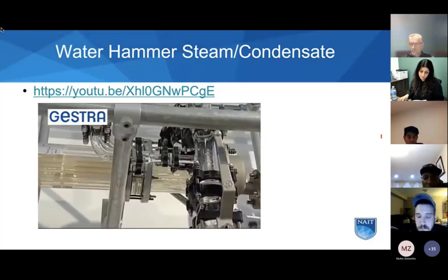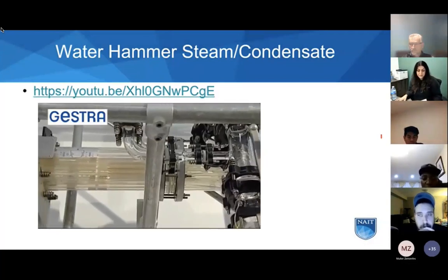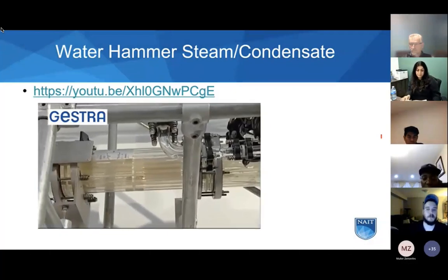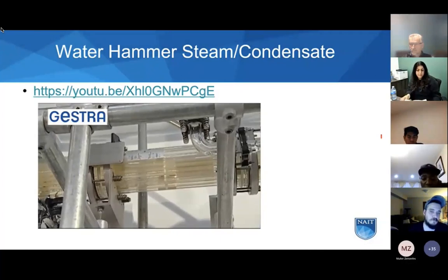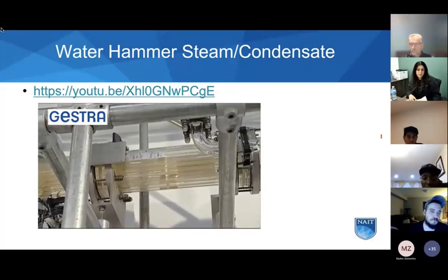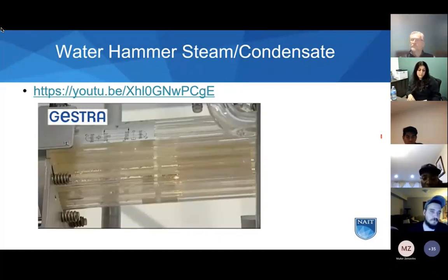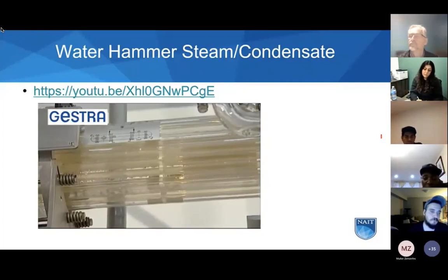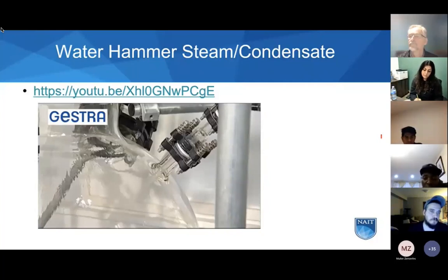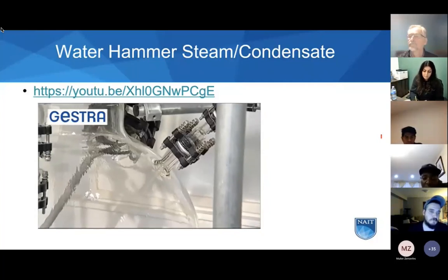As the condenser, we are using a glass heat exchanger mounted above the steam generator. Cooling water flows in the tubes, while steam flows in the jacket around the tubes. After passing through the steam traps, the condensate is collected in a glass condensate tank at normal atmospheric pressure.